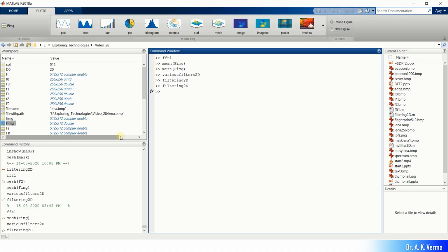So that's why we prefer the Gaussian filter over the ideal filters, to avoid such unnecessary ringing artifacts. Okay, a similar output you can achieve from the Butterworth filter also, because it also has the smooth transition.